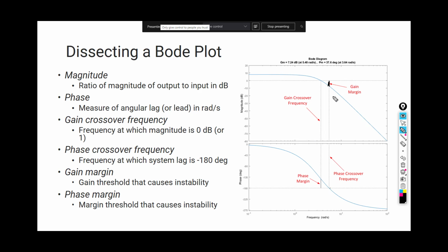Okay, that's the gain margin. You take the gain margin from minus 180. So the phase margin, you take it from 0 decibel. So you go to 0 decibel and you count how far you are from minus 180 and you determine the phase margin.